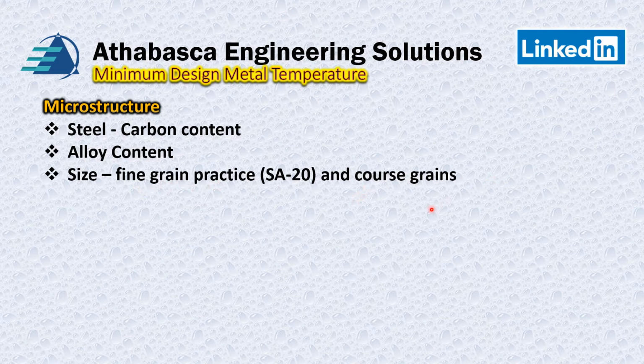Coarse grains are never great. They can occur around weld zones because there's more time for the grains to grow, and from poor heat treating practices. Coarse grains can lead to a much higher MDMT for the materials, and can occur in a less processed environment.